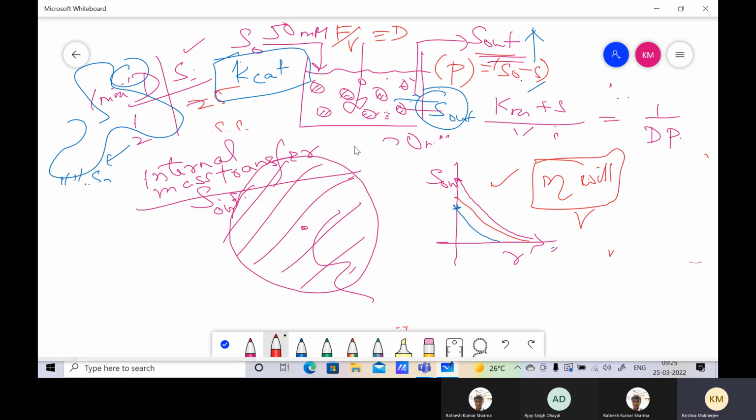We have now understood how to handle the CSTR. Why did I choose a CSTR in the previous class? I chose a CSTR because a CSTR has no external mass transfer control. Because of the mixing, there will be no film. The convective mass transfers are very good, right? So there is no film. So there is no diffusion control, because convective mass transfer ensures that the surface concentration here is S out. If I had a film, then the bulk would be S out, but the surface here would be something else, which would be external mass transfer control.